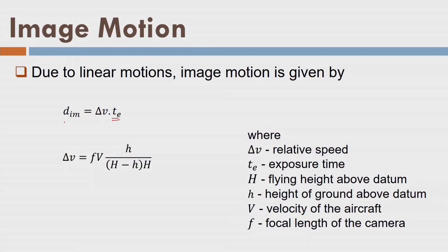Again, imagine that point, if aircraft is stationary, it will come here. However, the image is moving like this, and as a result, by the time rays are reaching, they will reach somewhere else. So there is a distortion opposite to direction of flight, and this distortion is called image motion, or rather image of a point is moving.